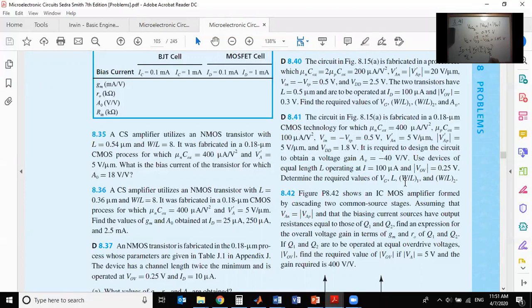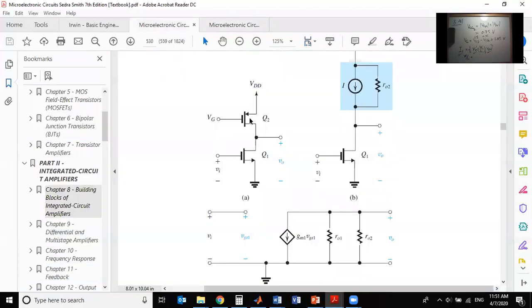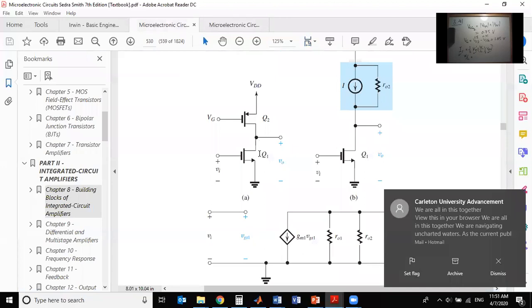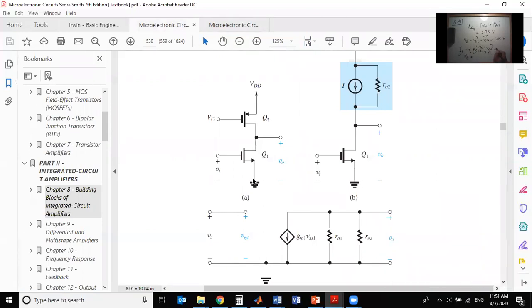What changes from the first to the second transistor? The width. Yeah, everything, but in this equation, other than W over L, is V overdrive the same? Yes. Is the current the same? Yes, because any current that goes through 1 will go through 2, right? Any current going this way will be the same, because you don't have any current going elsewhere. So I1 is the same as I2. So what's the only difference? The K values. The K and W over L. K in the first transistor is Kn, but in the second transistor is Kp.